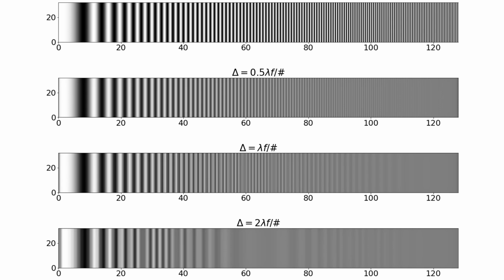And then if we undersample by a factor of 2, as in this third line, you see these high frequencies in this region occur as alias frequencies here, so they appear as lower frequencies than they are. And then here we've undersampled by a factor of 4, and that becomes much more pronounced, where we see these aliasing artifacts from high frequencies, and a null here. These nulls occur in the pixel transfer function. The optical transfer function has a smooth monotonic roll off, but the pixel transfer function has sinc-like behavior that can create nulls and then aliasing artifacts.